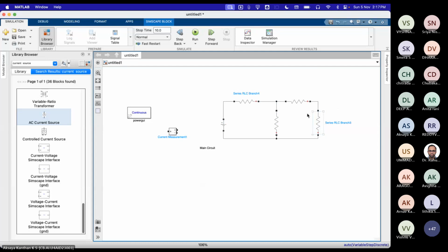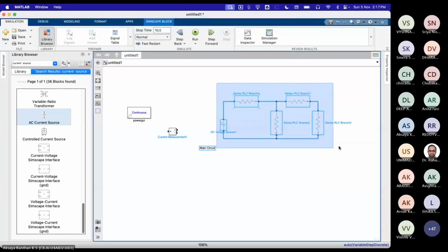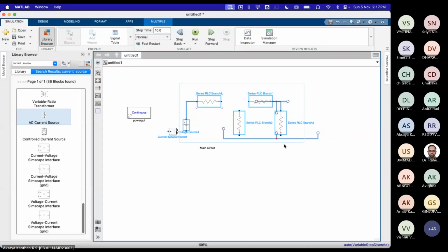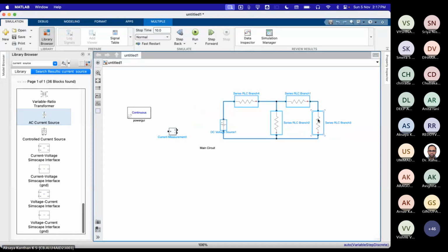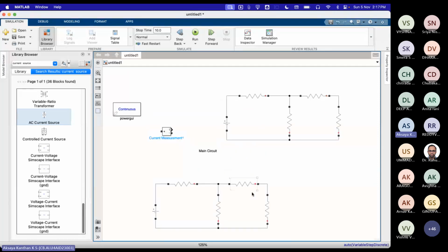So using Norton theorem, first of all, I'll duplicate this circuit, and then our first step is to remove the load resistance and then connect the terminals, and then measure the current through this terminal.